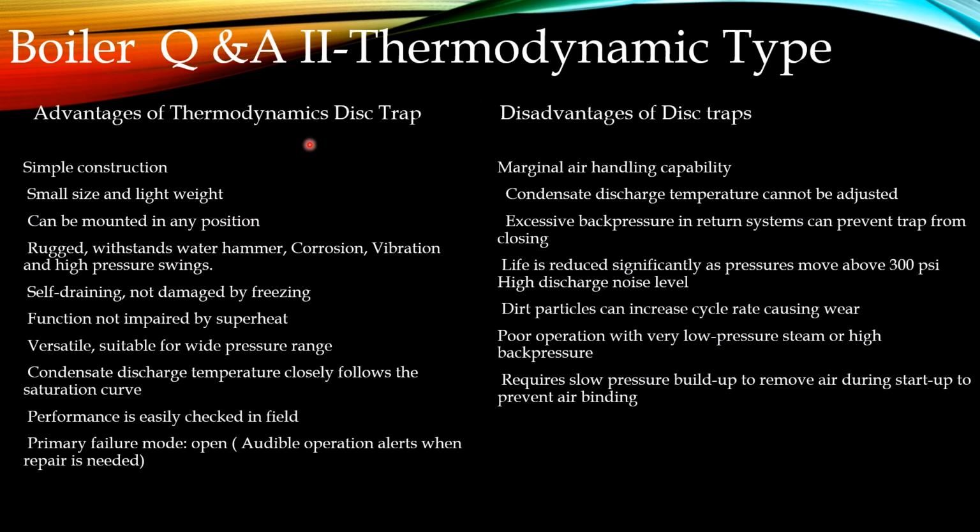Now we can see the advantages and disadvantages of the thermodynamic disk trap. Advantages are simple construction, small size and lightweight, can be mounted in any position, vertical or horizontal. Rugged, withstands water hammer, corrosion, vibration and high pressure swings. Various pressure swings also it can be used. It withstands water hammer, it will not damage. Corrosion also it will withstand and vibration also it will withstand.